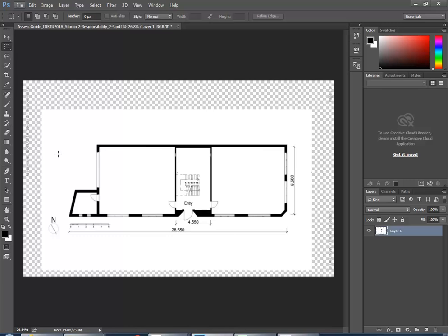Sometimes you'll be told that north should always be vertical, but that's really only for engineering and survey type drawings. Even surveys, they tend to orient them like this. So it's okay to have north off at a slight angle if it means you can have your plan at right angles. So the walls, in other words, in your plan at right angles, or horizontal and vertical. So that's the way we want it to come into Revit.